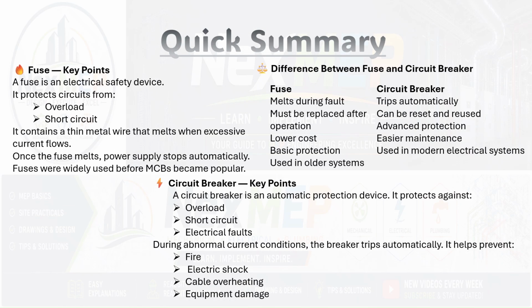Let's quickly wrap up everything we learned today. Fuse is a simple electrical safety device containing a thin metal wire. When excessive current flows, due to an overload or short circuit, the wire melts and automatically cuts off the power supply. It provides basic protection but must be physically replaced after every operation. Fuses were the standard before MCBs, miniature circuit breakers, became widely adopted.